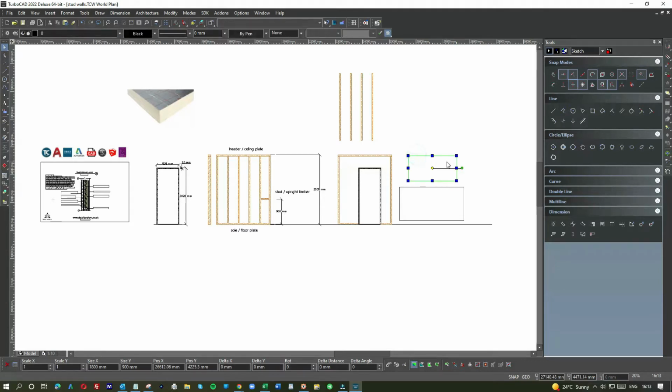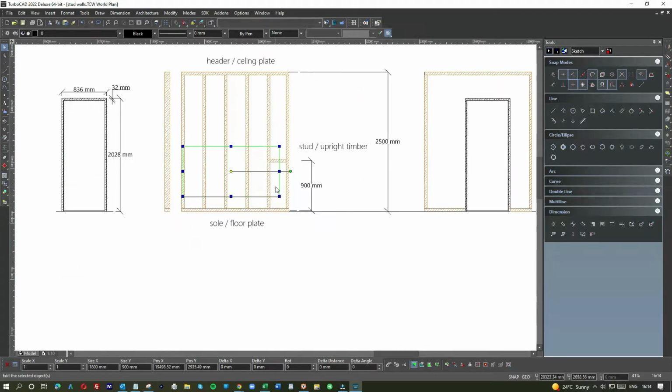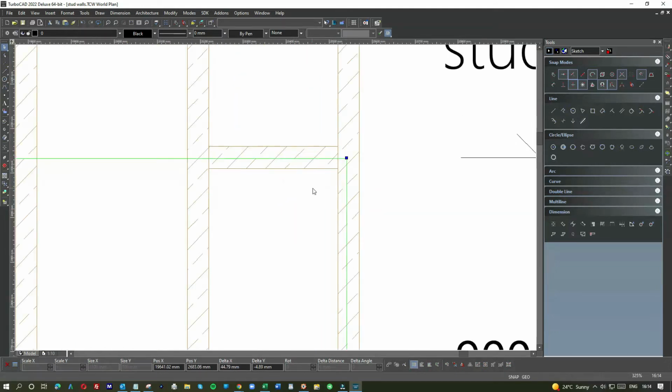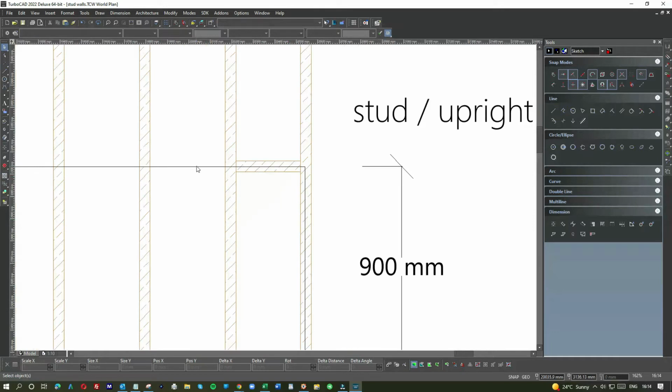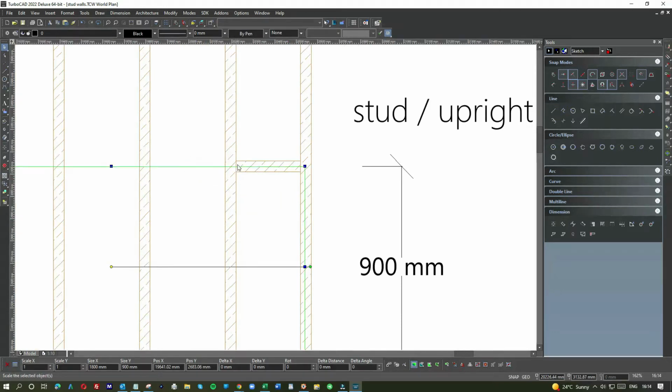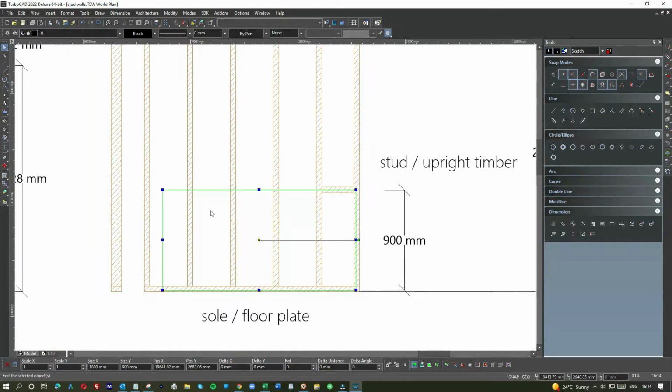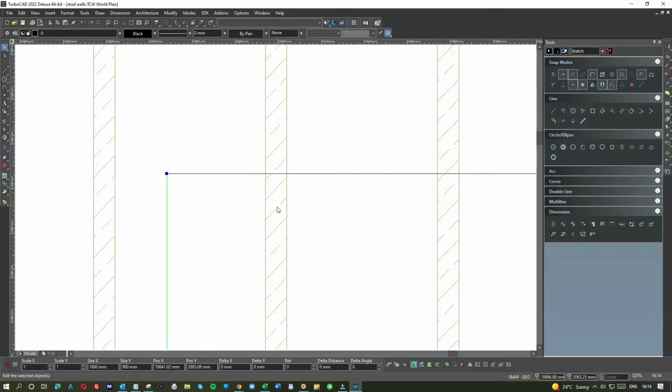So for example, now if I was covering the wall with this plasterboard, I wouldn't drop it on the floor. What I do is you generally go like so, yeah, so that it's center of the noggin, center of the joist, and so on. Okay, and here now you'd cut that plasterboard along this line in the center and get a new piece.